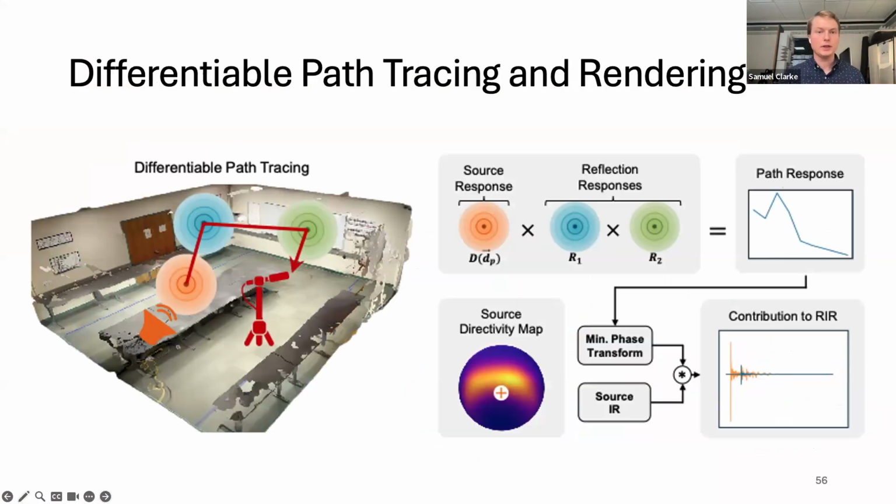However, if I were to try to go further in realism, I would take a rather different approach. First of all, these ray tracing or path tracing based frameworks don't model the interference effects of the waves as they travel through the room and interfere with each other. In order to do that effectively, you need a wave-based solver. Now, that would have been a lot more engineering effort.